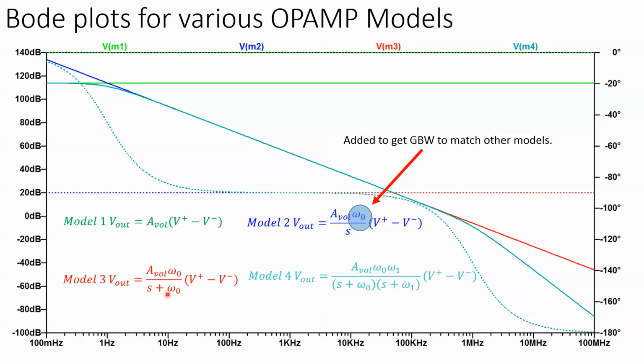For the first order low pass filter, that's red, you see a phase of minus 90, and it's being overwritten by the second order. It's on top, so it comes there. And then the phase for the integrator is minus 90 the whole time. Right, and you can see it here, and then it gets overwritten by the other models.